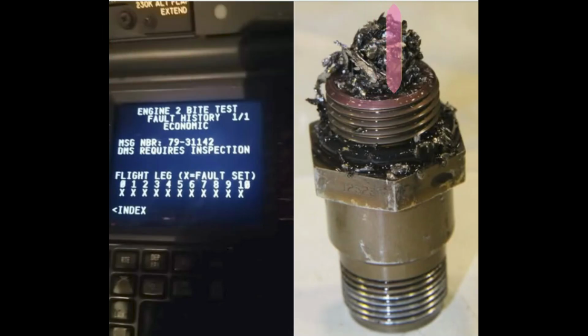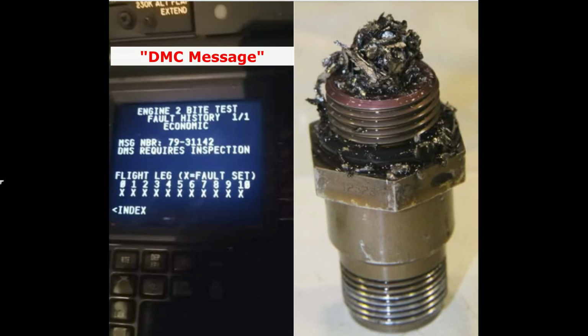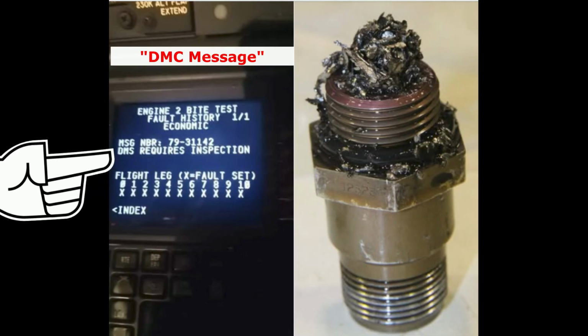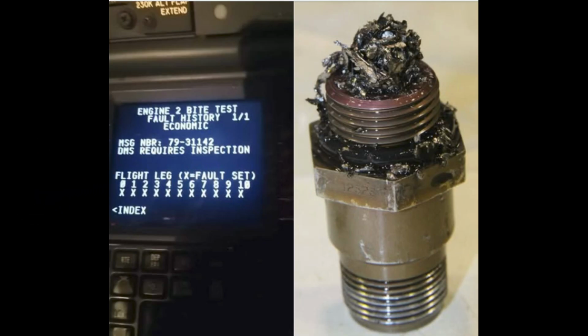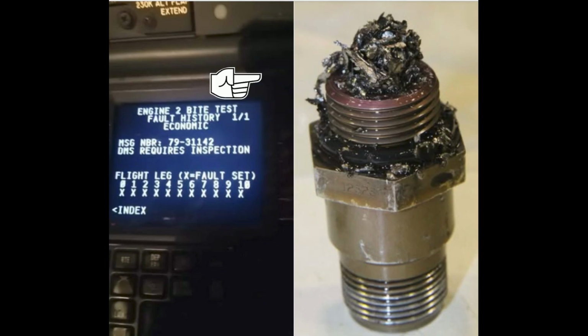Monitoring. The signal is then interrogated through the control display unit. Maintenance alert. In case of abnormal findings, a DMC message indicating check may be displayed. This message signifies that magnetic metallic particles exceeding acceptable limits have been detected within the engine lubrication system.